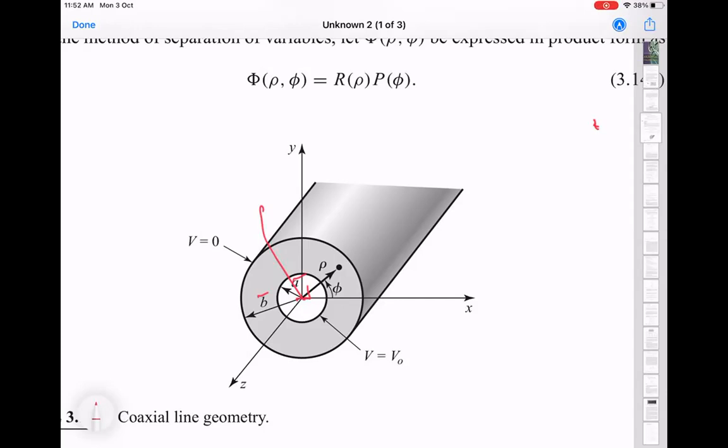So from the point of view of the coaxial line, it's the outer surface of this inner conductor and the inner surface of the outer conductor, which are the relevant boundaries you have to worry about. Okay. But the way they're usually constructed, the center pin is solid for practical reasons. So if the center pin is hollow, there will be TM or TE modes. Yes, that's right. That's what I said, that TEM modes won't be present inside that smaller tube.